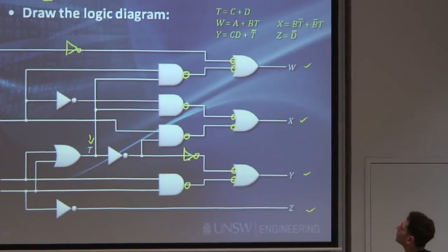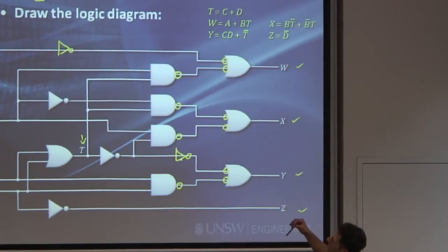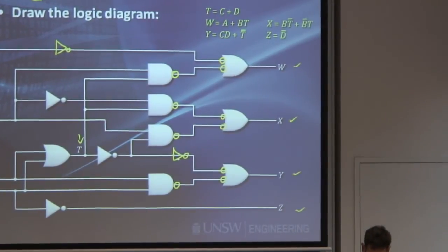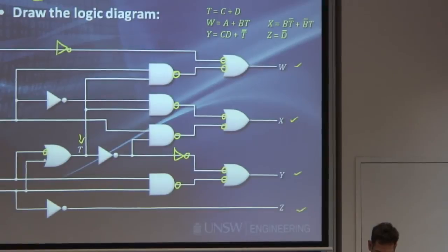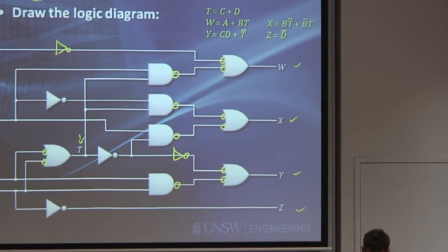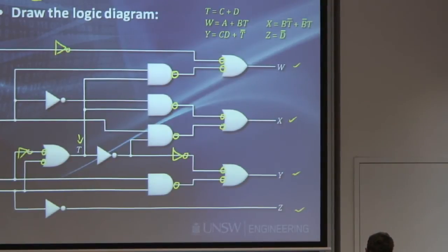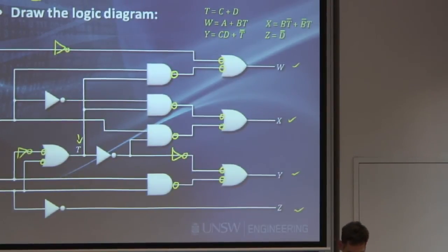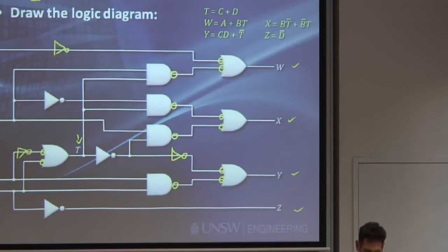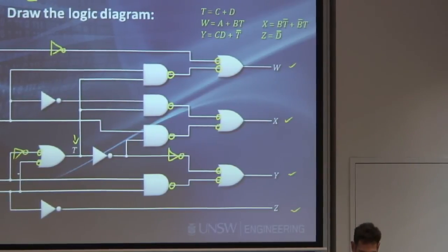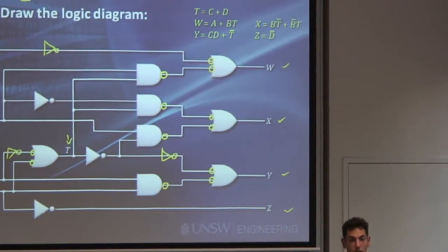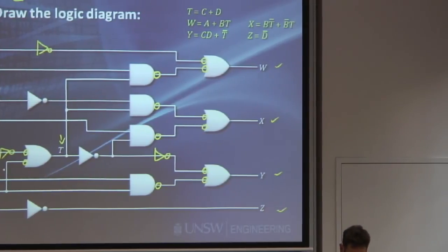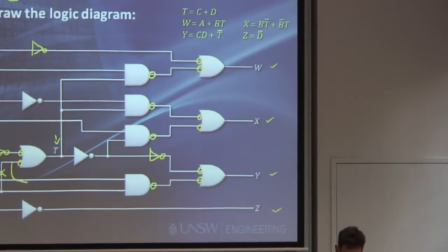So doing all of these, and then I think there's a couple more. There's this, because I do want everything to be as NAND. I will put an inverter here. And for this one, I could actually, instead of inverting it, because I'm already inverting the signal D, I will actually cross this line and connect this.